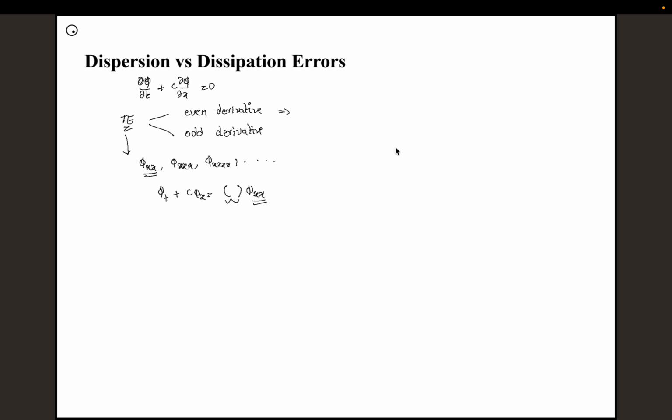If you compare this equation with the Navier-Stokes equation that we have in 1D, del u del t plus c times del u del x, where c is basically u there, this is the del square u del x squared term. So the term in the bracket is similar to the viscosity term. But here we call this the artificial viscosity, because this is introduced when we convert the original PDE into the discretized form, the finite difference form.